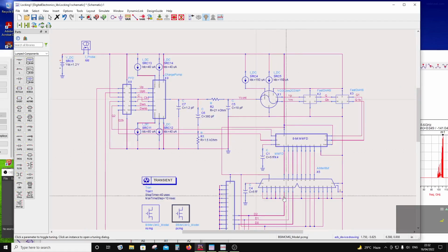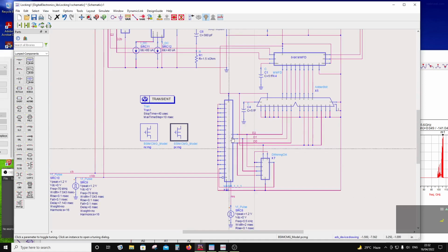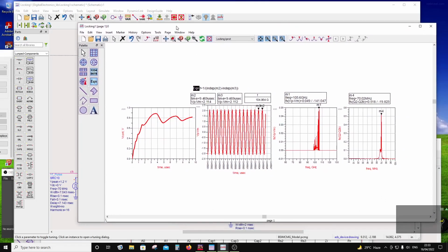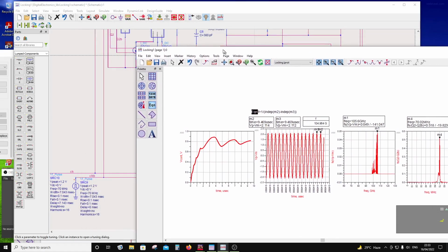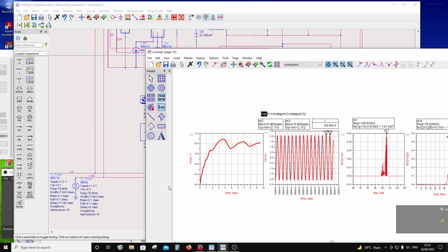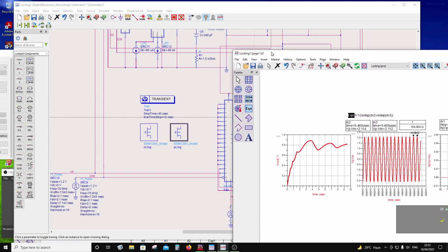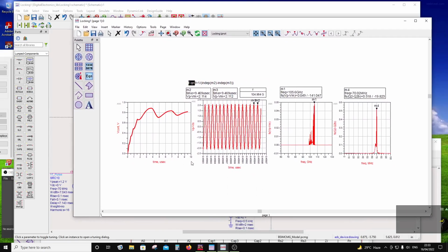For example, there is a 16-bit sigma delta here for the fine feed. 16 bits means 2 raised to 16, which is 65536, and with 70 megahertz, 1 over 70 megahertz times 65536 is around 1.3 milliseconds. To have an exact fraction, you might have to simulate for 1.3 milliseconds, since the exact ratio will be given by the sigma delta. That simulation time I could not run because it's a very long simulation.